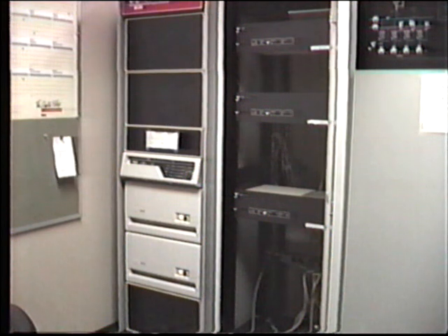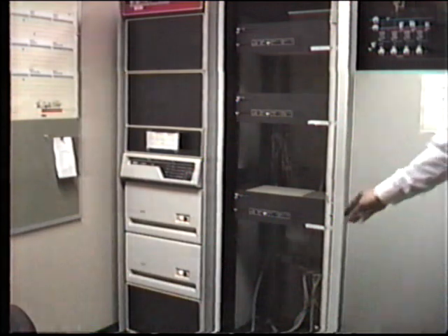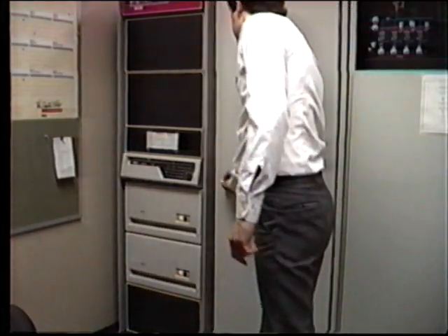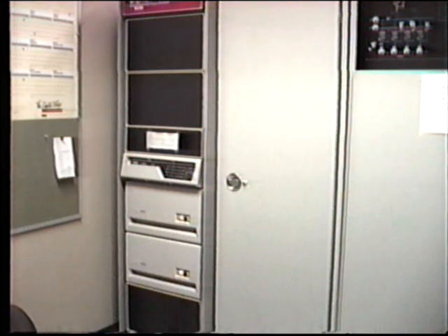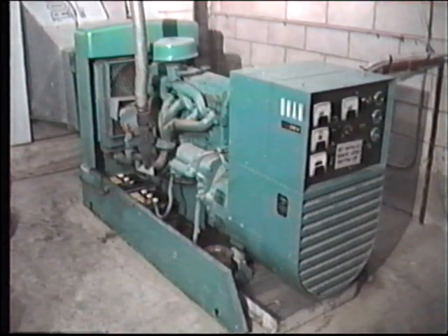Right. Now, let's take a look at the master station. The computer equipment is usually installed in the system control center, often in a separate computer room. It is essential that the room be equipped with reliable air conditioning to maintain controlled climate conditions. Power supply to the computers is provided by a battery bank, which itself is part of an uninterruptible power supply system. A standby diesel generator is usually installed in case of an extended loss of AC.